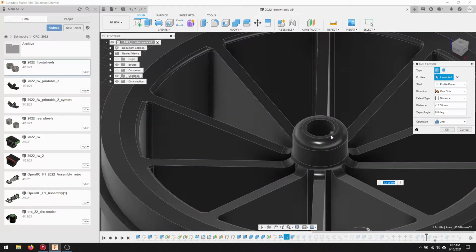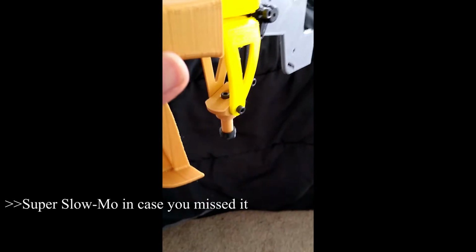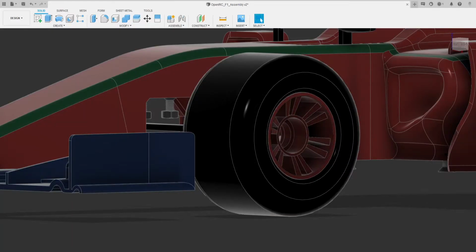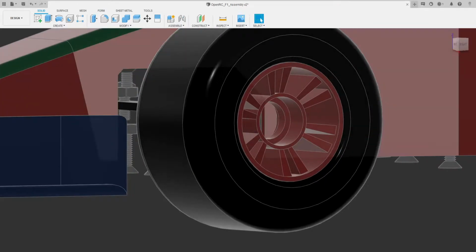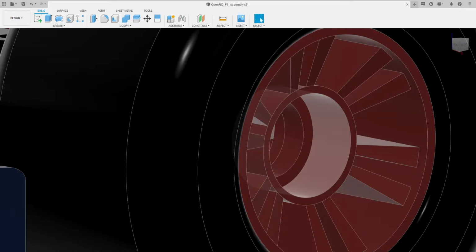I resized the inner hole to fit the bearings and removed the wheel nut. While the rims did fit, even with the wheel bolt on the wheel, it kept falling off. Then I took a closer look at the original front rims and realized there's a constricted section in the middle that separated the axle and the bolt, which I had missed.